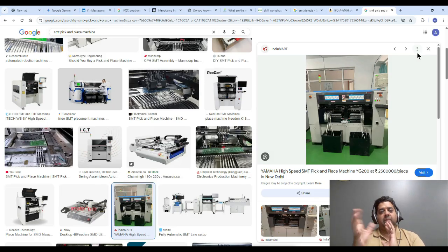So the programming aspect: during the program, first of all, the engineering has to figure out how to do the pick and place, what path. They have to figure out the path, and then the SMT engineers will need to figure out which nozzle to use for which component. Okay, so that's one thing.